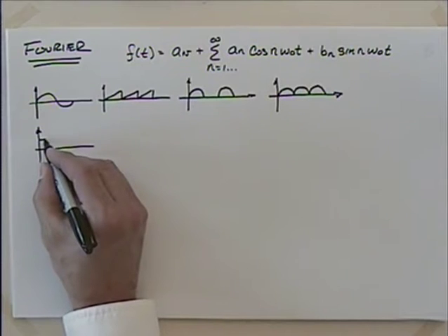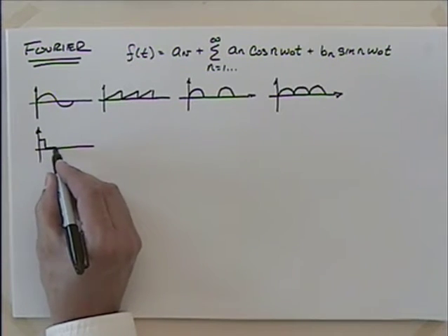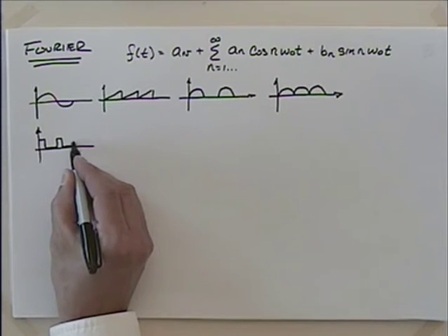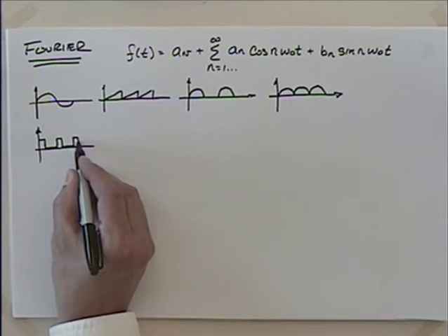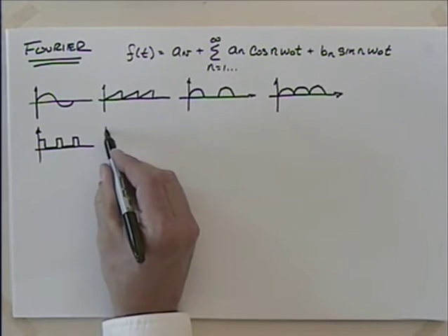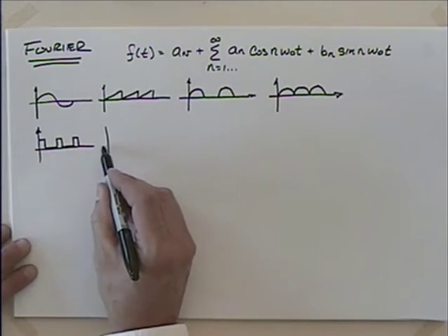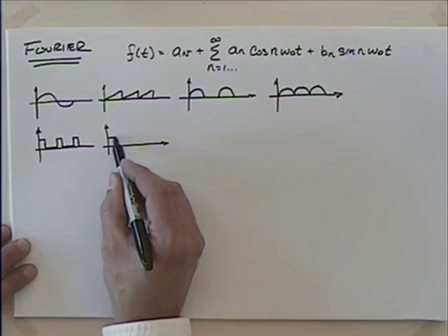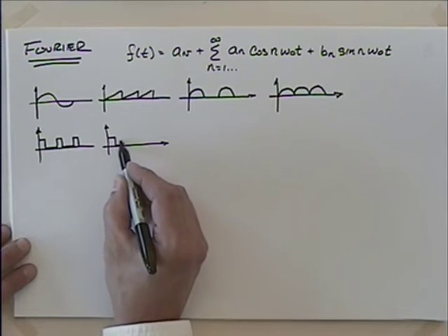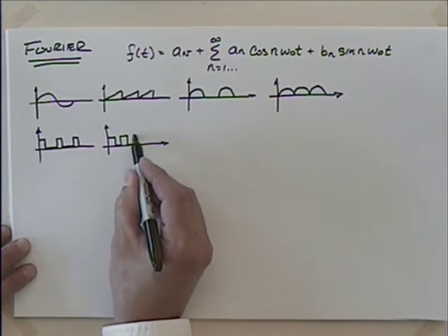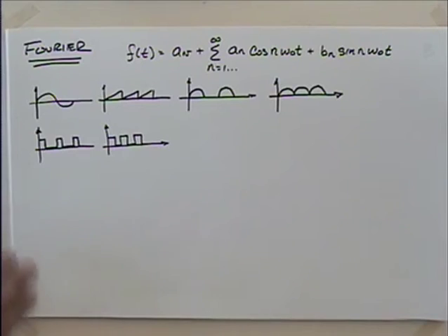What we do is we turn it on for a while and then turn it off, and then turn it on for a while and turn it back off, and essentially manufacture a signal like that. If you want the fan to go faster, or the lights to be brighter, what do you do? Leave it on for longer, and then leave it off for a shorter period of time. So we'd have something like that.